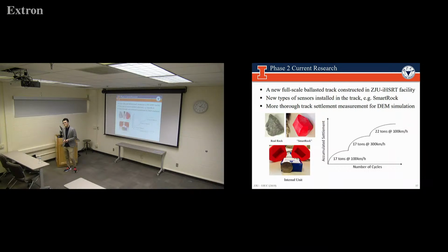How do you decide that the compaction, construction-related density and compaction densities or void ratio, whatever, right, can be actually determined, measured, and obtained, and that's an input for your model, right? You need to match the initial conditions to start, especially for settlement calculations and predictions. How do you get that in the field correctly measured?